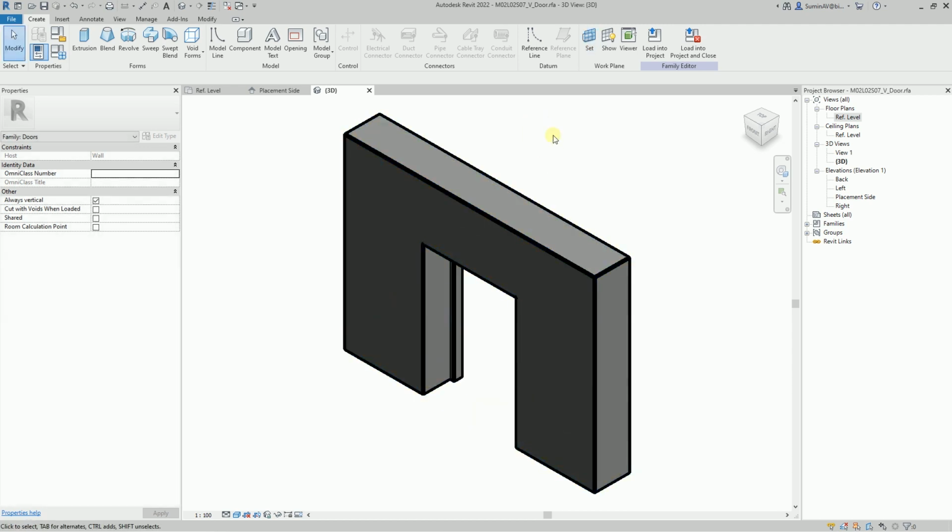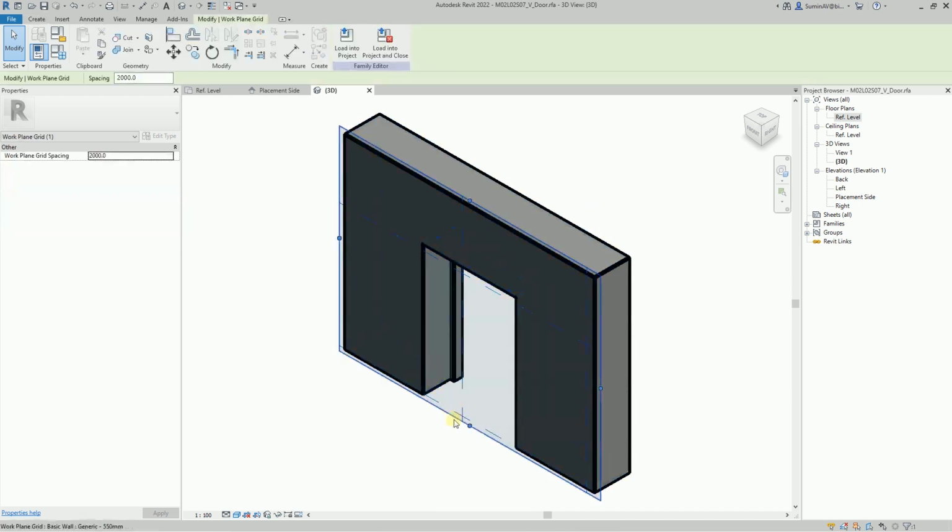In addition to the ability to view the workplanes in a special 3D view, if we are already in the 3D view, we can simply click the Show Workplane button, and the workplane will be highlighted. This command works on all views, but if you use it on a plan view or on an elevation, it will not be clear enough there which plane is the work one. But in the 3D view, it is quite obvious.